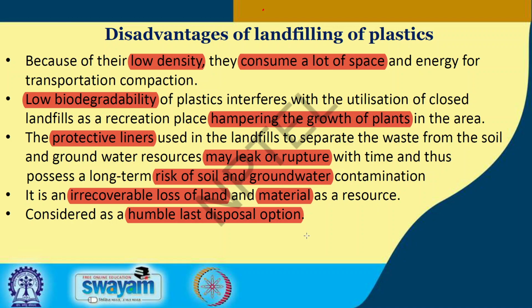The presence of plastic in the landfill will hamper the growth of plants in the nearby areas, and the protective liner we have used at the bottom can have some rupture and leakage. Again, leachate will enter into the groundwater, and there is a risk of soil and groundwater contamination and irrecoverable land loss. So we have to consider landfill as a humble last disposal option.